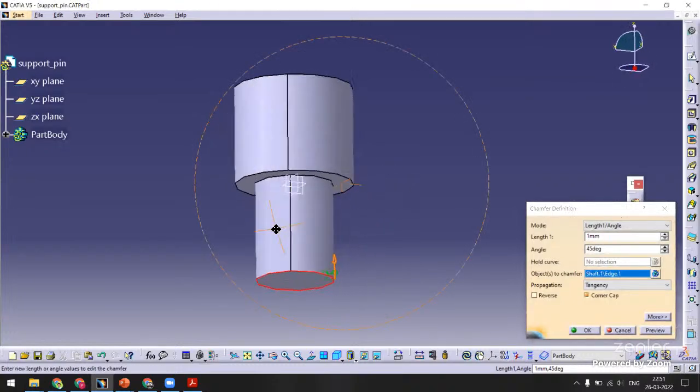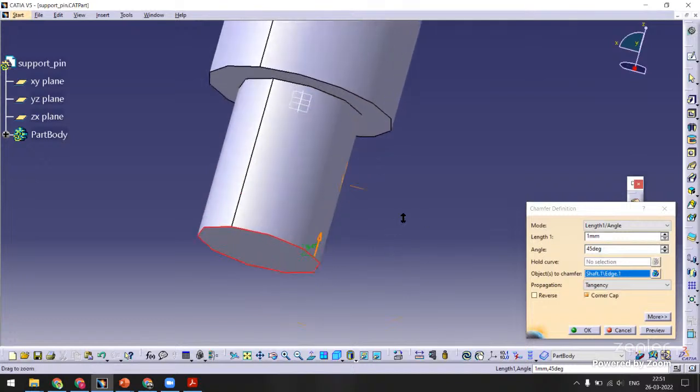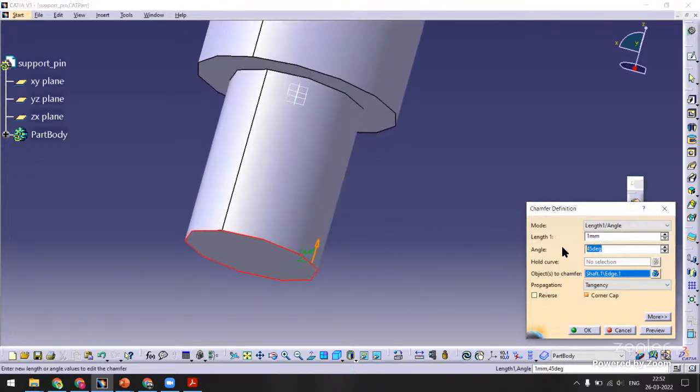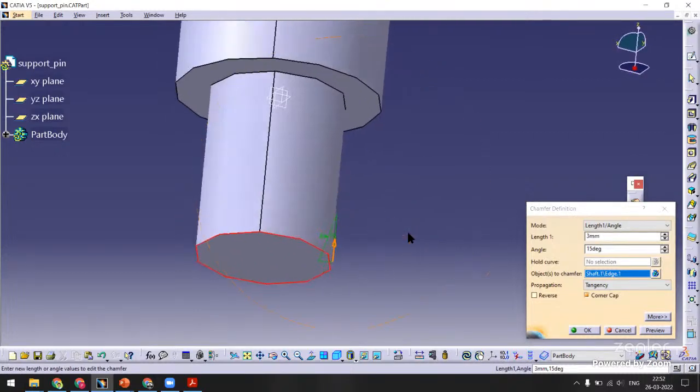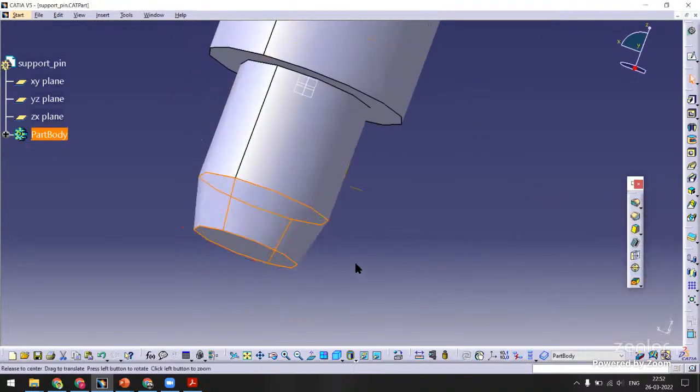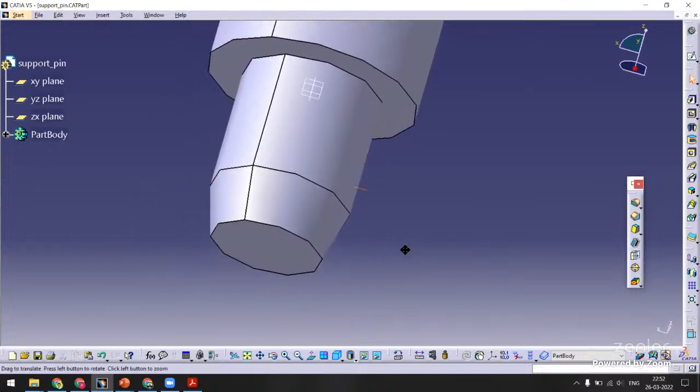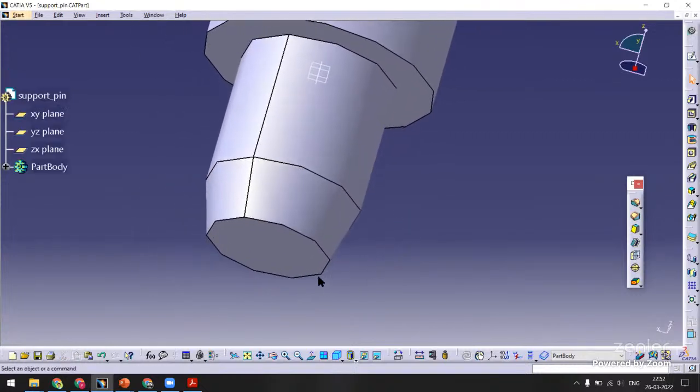So generally, this is called an entry chamfer. So generally entry chamfers are of 15 degree. Probably I'm going to make this 3 mm. How do you decide it as 3 mm? Okay, this all comes with experience. So you'll have to do many projects. Let me preview and then tell. Yeah, now this looks good.